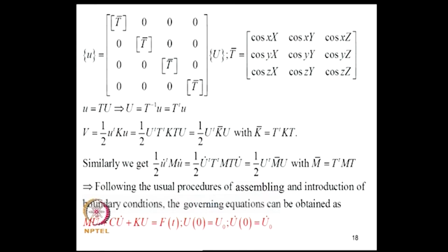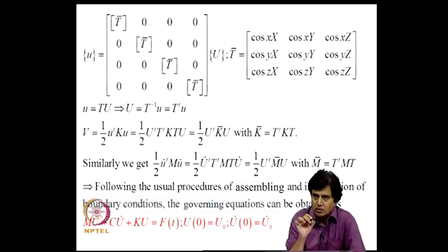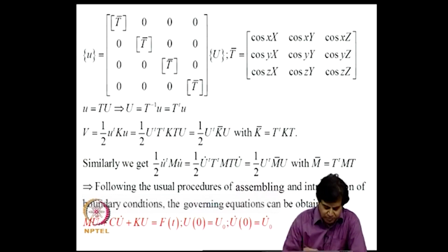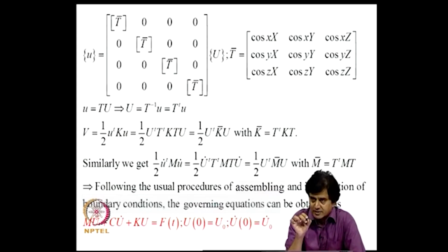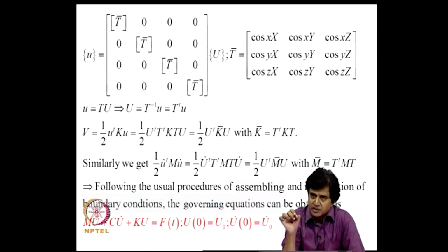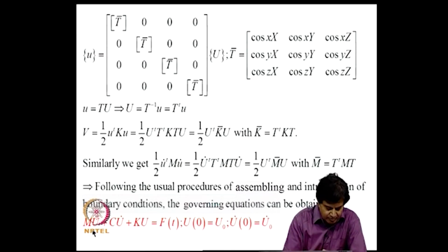So, you need to write the element equation of motion for every element and then take it to the global coordinate system, convert the node numbering to the global node numbering scheme, and follow the usual procedures, then impose boundary conditions, partition the state vector into those components which are not known and those which are specified, and for the unspecified displacement vector this is the final equation of motion.